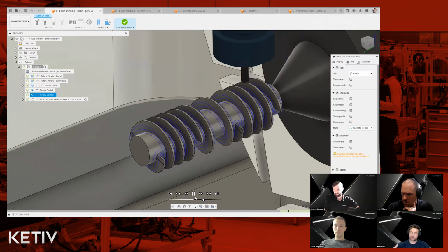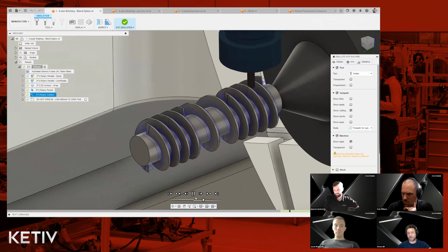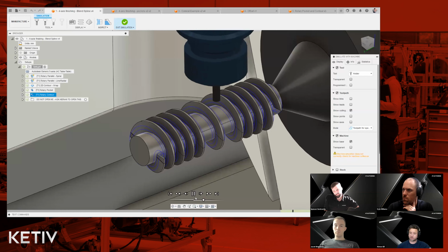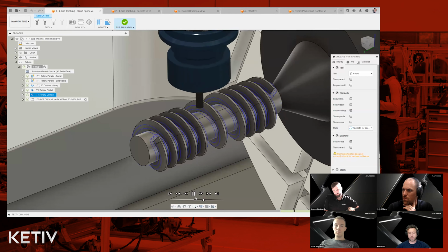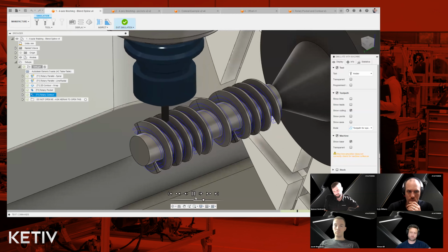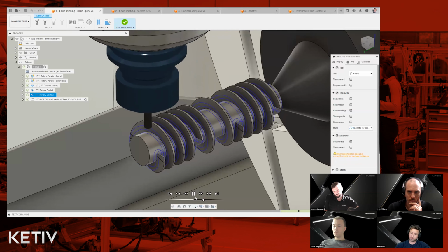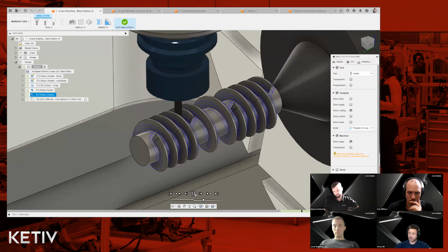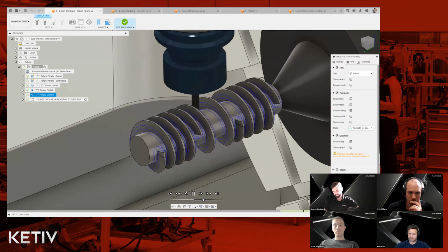a wall finishing strategy. So the idea here is you use the rotary pocket to come out and rough those cylindrically feature-rich parts or conically feature-rich parts. And then you come in with that rotary contour style strategy to beautifully clean up those walls and end up with a beautiful surface finish. So that's some of the problems, highlighting how they're overcome by these two new toolpaths.